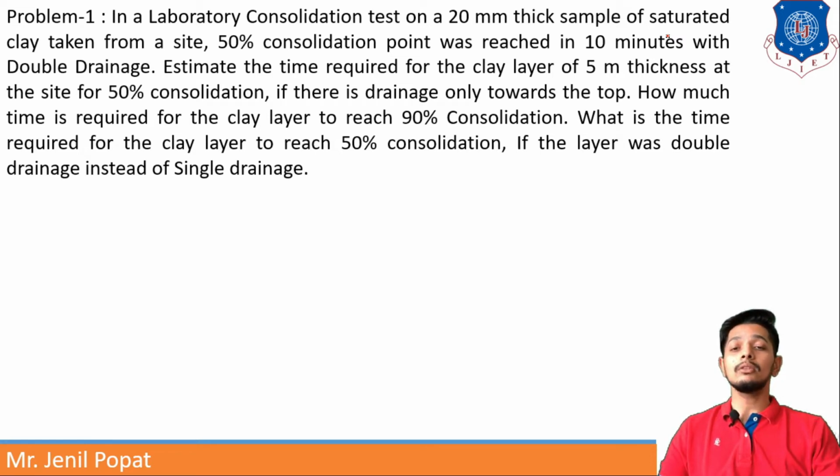Now, if the layer is 5 meter thick and drainage is only towards the top, it is a case of single drainage. How much time is required for the clay layer to reach 90% consolidation? So the time is asked. What is the time required for the clay layer to reach 50% consolidation if it was double drainage? So it is a complex problem. Let us solve it one by one.